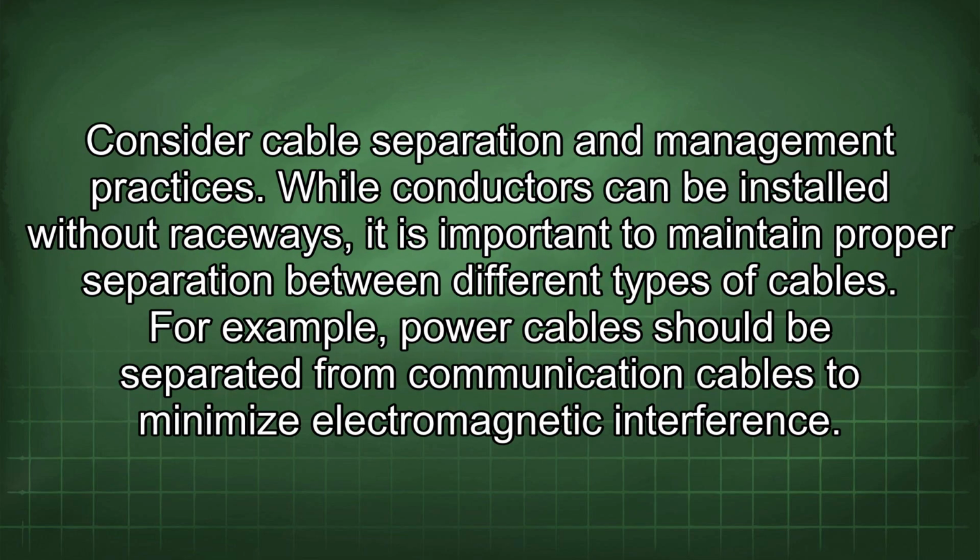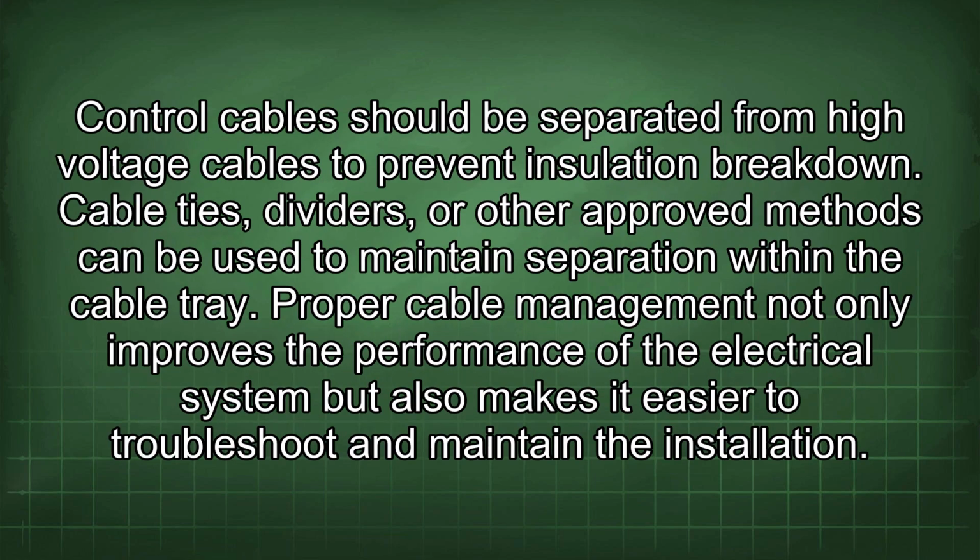Consider cable separation and management practices. While conductors can be installed without raceways, it is important to maintain proper separation between different types of cables. For example, power cables should be separated from communication cables to minimize electromagnetic interference. Control cables should be separated from high voltage cables to prevent insulation breakdown.